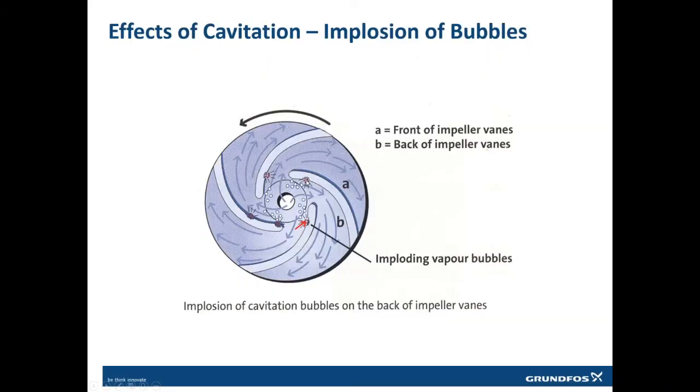Why is this happening? Because these small water bubbles which are coming through your suction are hitting and imploding on the back side of your impeller. If you can see here, all of them are imploding on this side of your impeller.